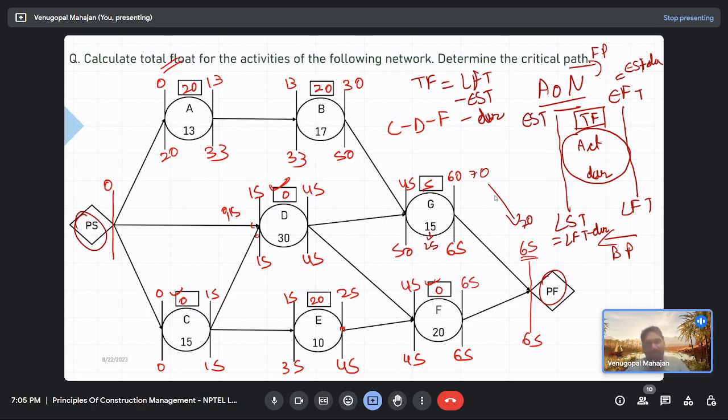So you can see that total float is giving you an idea of what relaxation or how much float you actually have for each activity. Like if activity A delays by 15 days or 18 days or even 20 days, you are sure that it is not going to affect your total project duration, right? But if it delays by even 21st day, you know that that one day is going to be seen in your project duration. So that is one way of looking at total float.